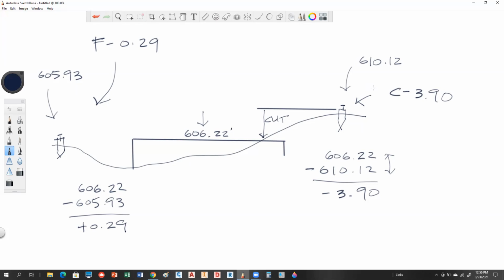All right, radial stakeout is another question. There was a question on that problem too, so you're liable to have to do something like that as well on that test. So what I'm saying is we have a control point here, and we have a control point here, and we have something that we need to stake out, okay? So we would know a coordinate, coordinate, and coordinate.